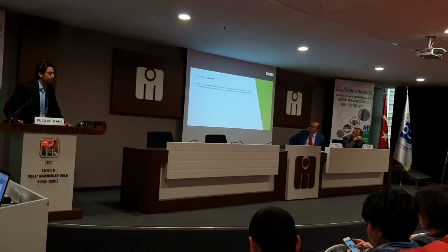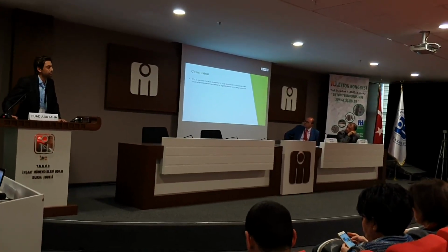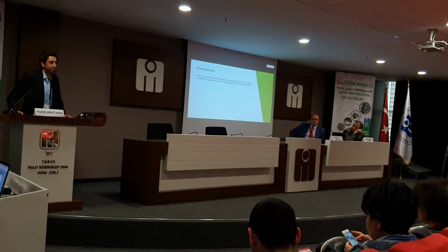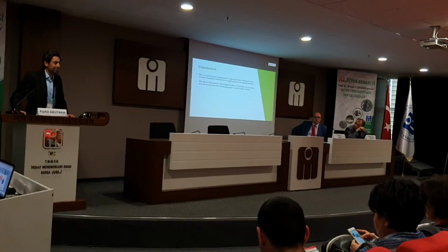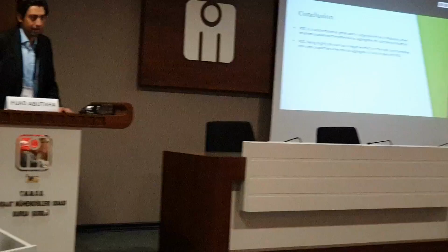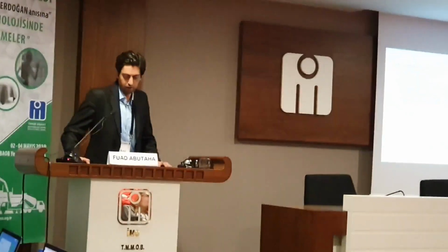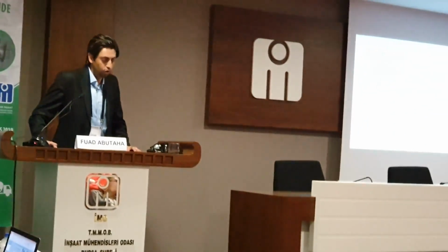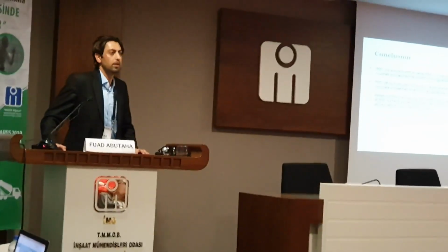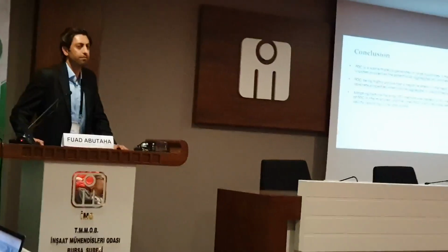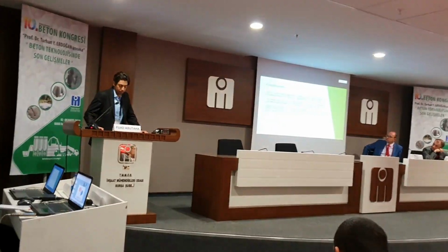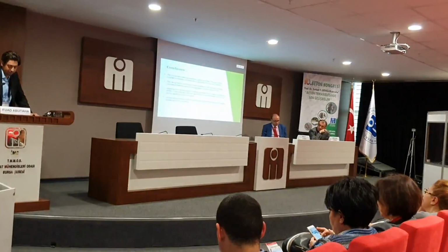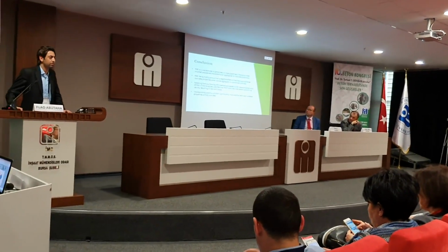So in conclusion, POC is a waste material generated in large quantity, and when crushed it possesses the potential to be used as aggregate in concrete production. POC is a highly porous material and has a negative effect on the fresh and hardened properties of the concrete, but adopting the particle packing method is beneficial to measure the volume of voids in the mixtures, and incorporating additional POC powder significantly improves the fresh and hardened properties of the concrete.